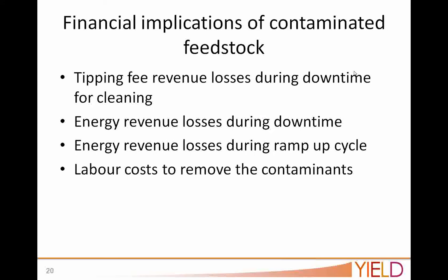So if your digester is filling up with contaminants faster, and also I should add that the more water you use, it actually drops your total solids faster, and so you're going to have increased settling of the grit fraction and separation of contaminants as well.